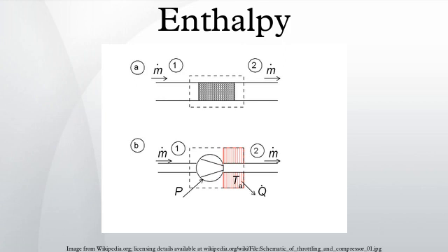The term dV_k/dt represents the rate of change of the system volume at position k that results in pressure-volume power done by the system. The parameter P represents all other forms of power done by the system such as shaft power, but it can also be, for example, electric power produced by an electrical power plant.